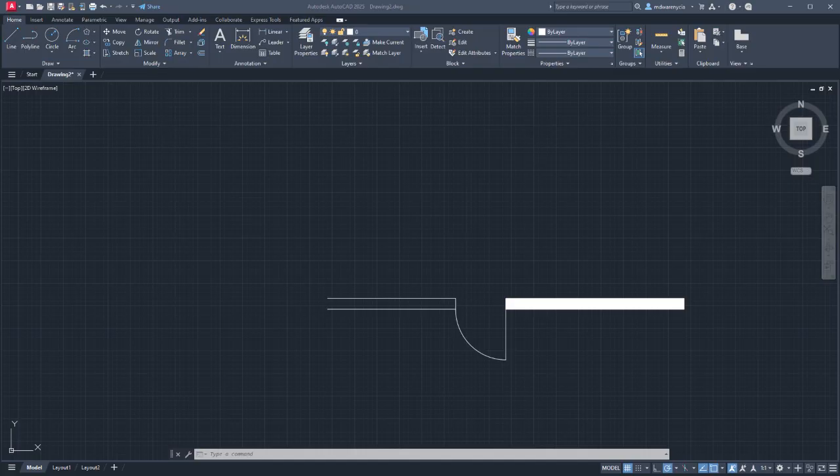So maybe I scale something up and I thought I scaled it, but instead of being 10 foot by 10 foot, it's 9 foot 11 3/4 inches or something. Scale introduces a lot of problems in your models, so I would not use it early on until you're more comfortable with the program and you understand that just arbitrarily scaling things can cause problems. So if I have a table and I scale it up slightly, maybe that table that I had is no longer 6 feet on one end, it's 6 foot 7 1/8 inches or whatever.